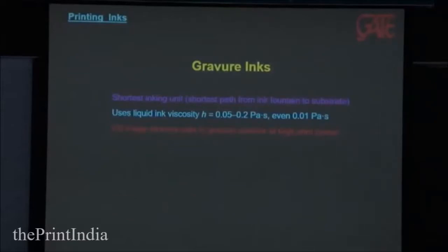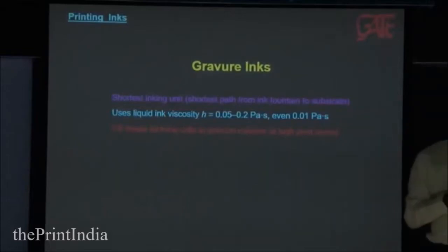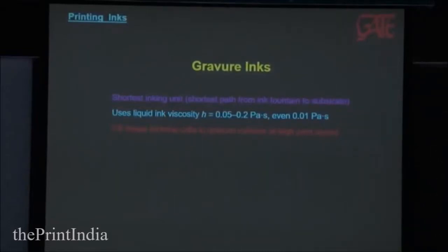Okay. So here you have a similar problem: if ink dries in the cells, you will get variation. If your impression cylinder doesn't have the right Shore hardness, it doesn't give the right impression. If your substrate web is not right under the impression cylinder, then also you will not get the right transfer of ink from the cylinder.